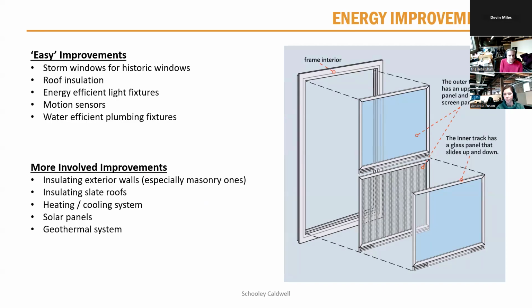If you start getting into bigger renovations, you can look at insulating the exterior walls, though again, that's something you need to be very careful about. Same thing with if you have a slate roof. Slates need to breathe. Absolutely contact a professional before you insulate a slate roof, because you do not want to cause damage to a roof that is otherwise a very long-lasting roof.